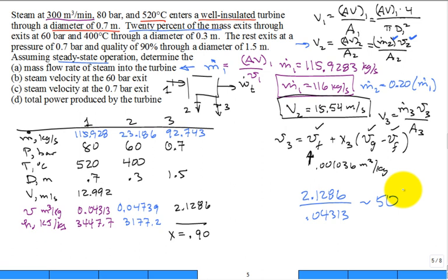It's dropping pressure and expanding as it pushes the blades in the turbine and transfers energy to the blades of the turbine and produces work for the turbine. So 50 times expansion. Very good. So now, once we have that specific volume, the same strategy for the enthalpy, isn't it? And so the enthalpy comes in after some calculations of 2431.67.